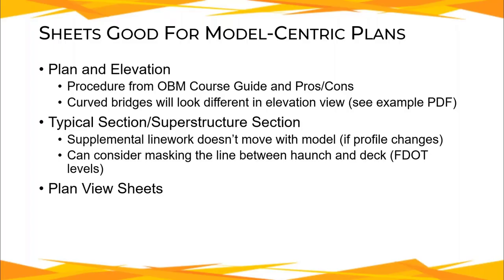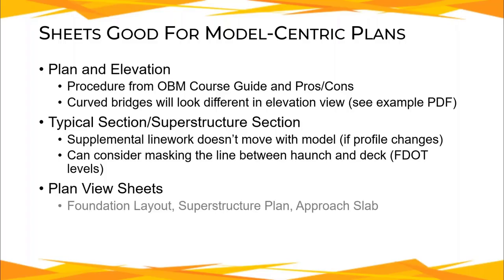And plan view sheets, these are generally pretty good, pretty easy to do with the name boundary tool. So we're talking foundation layouts, superstructure plans, approach slabs, anything that you want to get more plan views of. Those usually work out very well with a 3D model because you're turning all the 3D stuff off and you're just using the 2D decor levels, or we call them decoration levels.